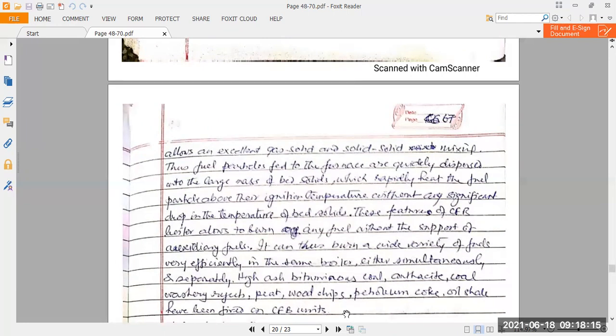So this particular feature of a high amount of residuals, sorbents and ashes inside the huge furnace creates an extremely high temperature for burning any newly injected fuel. This gives us the support of using many different types of fuel, not only extremely high quality fuel.